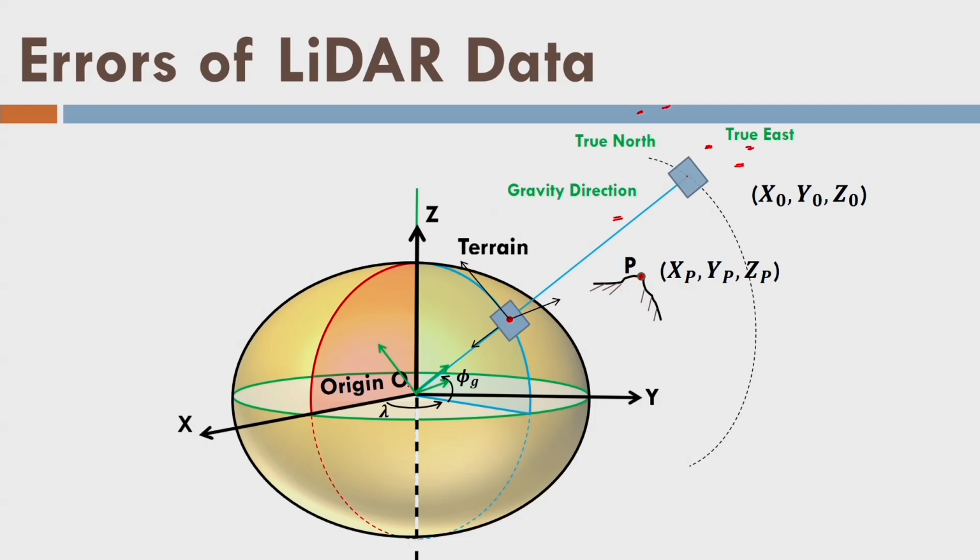So, I can write this reflection as well as the transformation matrix. The inclination and reflection is indicated by this: 0, 1, 0, 1, 0, 0, 0, 0, minus 1. Here you can see that I am changing x to y and y to x, as well as flipping the z axis by minus 1, and then we are doing the translation by x0, y0, z0 like this.